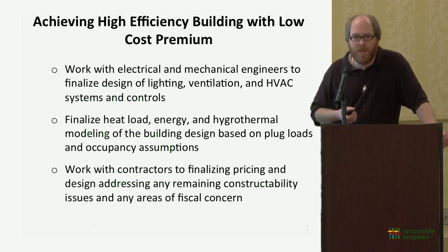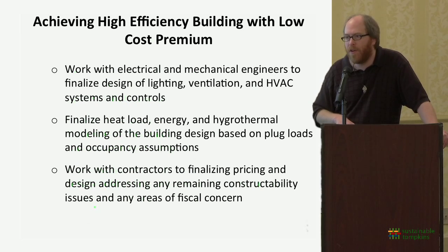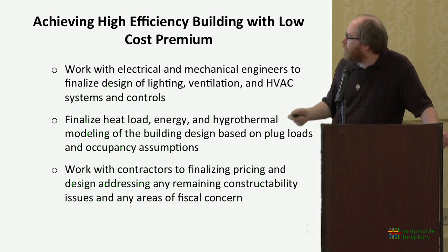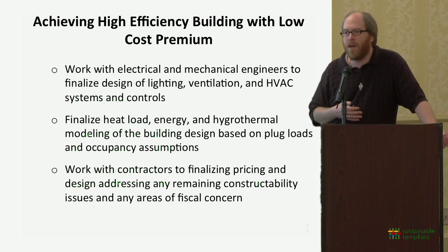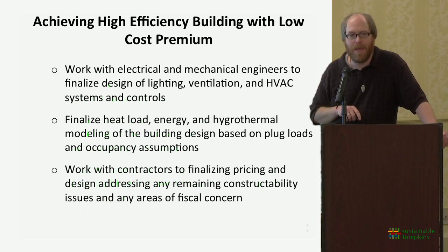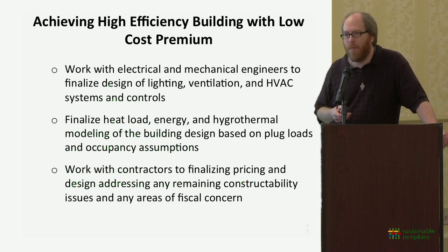Then we come, of course, with the final design for the actual systems, when you have the electrical engineers and the mechanical engineers with the HVAC and electrical systems. You want to integrate the controls at the same time. The simpler the controls, the better. If you have people needing to program complex systems to make the building operate at high efficiencies, that's going to create more operational complexity.